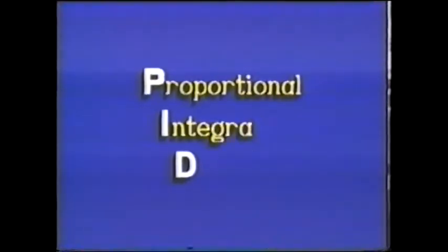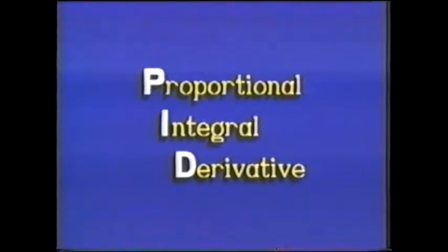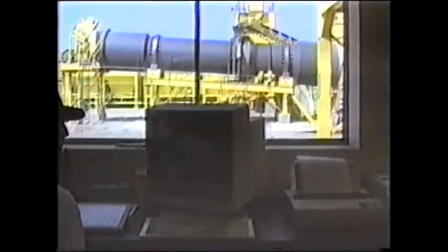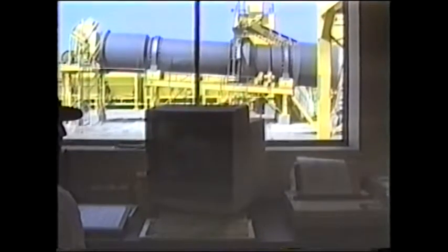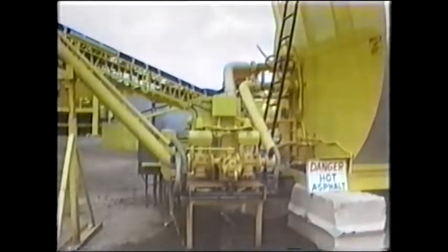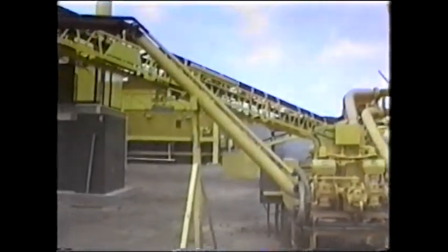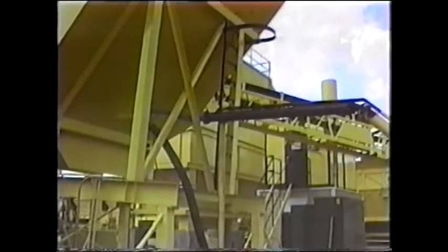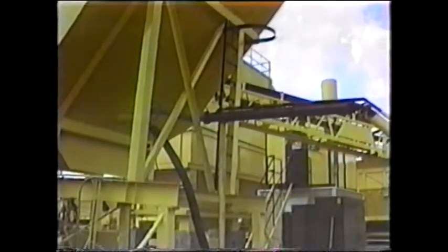PID technology is used to control each material that goes into the process. PID is a sophisticated control technology that offers the ultimate in accuracy and system reliability. Operator error is virtually eliminated and efficiency is drastically increased. Also, to eliminate waste, the asphalt line is automatically cleaned between mixes. This means that the pump is reversed and the line is cleared so that the asphalt ejection time starts from the same point on every run.